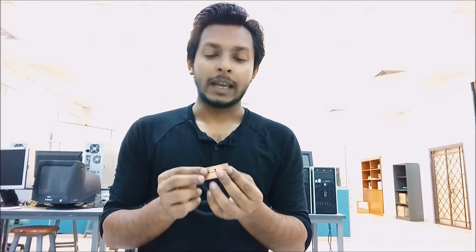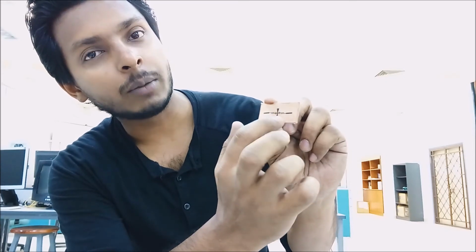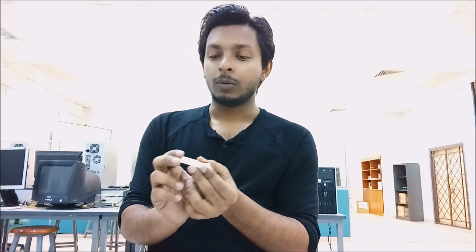We will make a solution, and we will keep this inside the solution for hours until all of these copper areas are removed all the way, apart from only these black areas. So only this black portion will be like this, and all the uncovered copper will be removed, and we want our substrate to be completely open, apart from these black areas. That's the basic concept of the etching process.